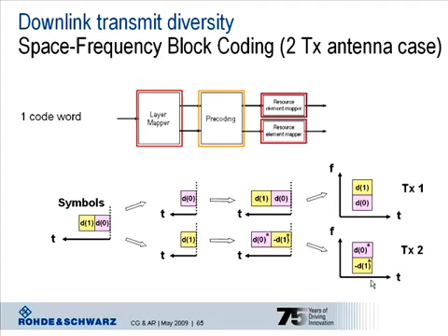At the same time, antenna 2 transmits the symbol D1 on this subcarrier, with a special coding applied for this symbol. And looking at this other subcarrier, it's vice versa: TX2 transmits D0 and TX1 transmits D1. So we transmit a redundancy of information, and we achieve an increased robustness, but no increase in throughput or data rate compared to the single antenna case. So this is transmit diversity.